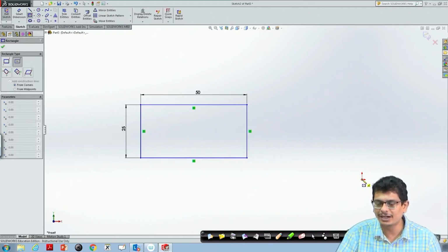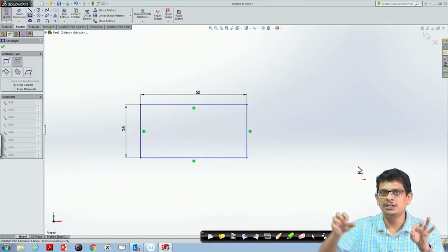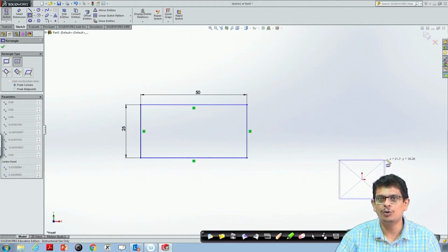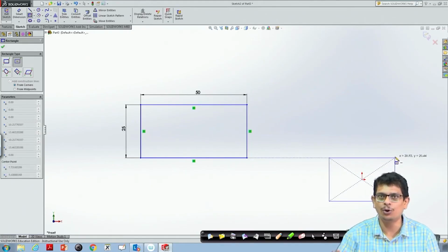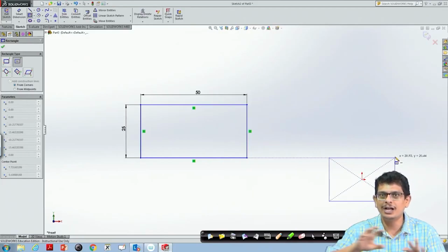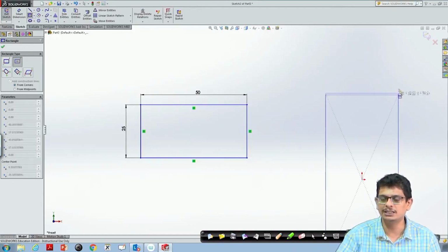Now, for that I have to pick one of the points. Pick means right now my hands are not touching the mouse. Now, I will move my mouse, give a left click on one of the points, then move. I am not pressing and holding it, I just click. So, it has selected that corner point. Now, I just move my mouse and release at different locations.